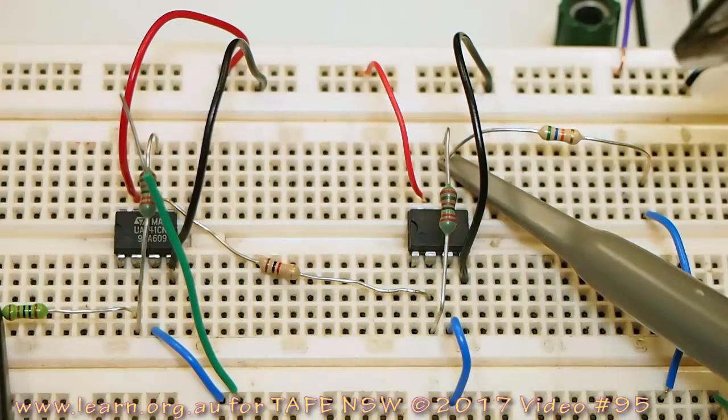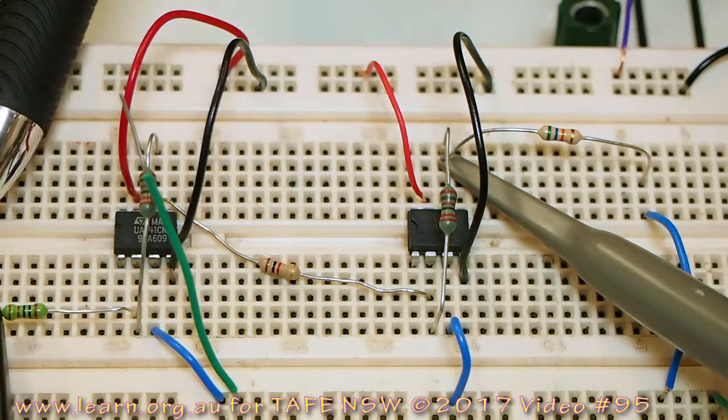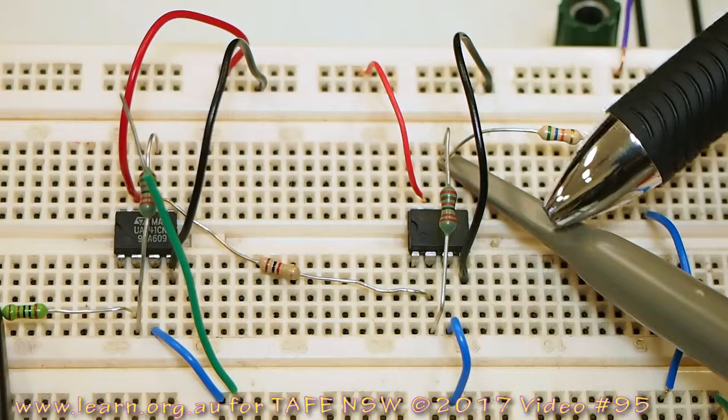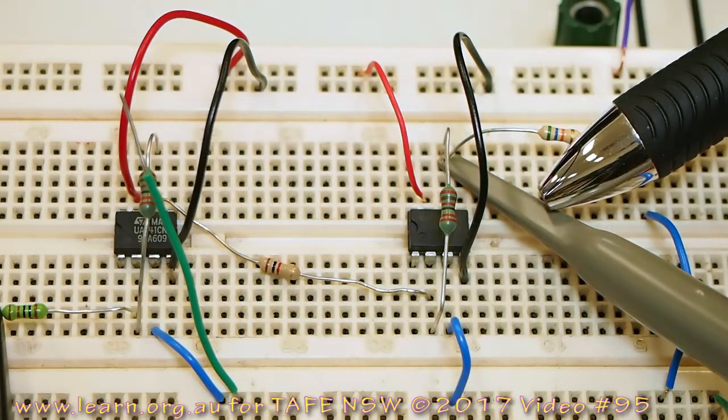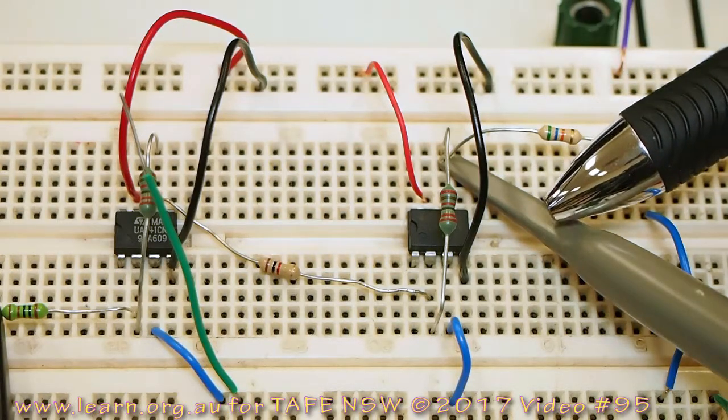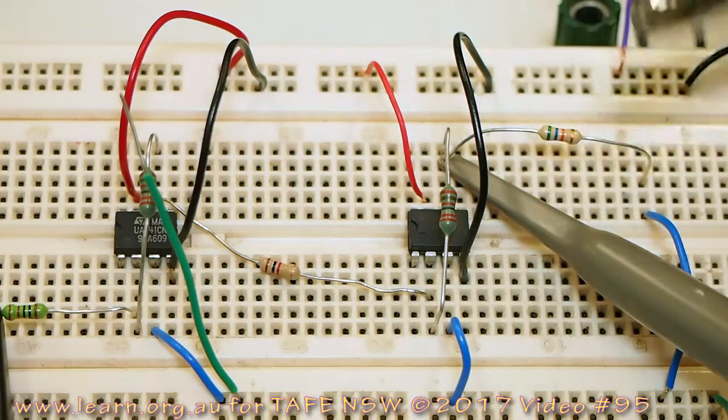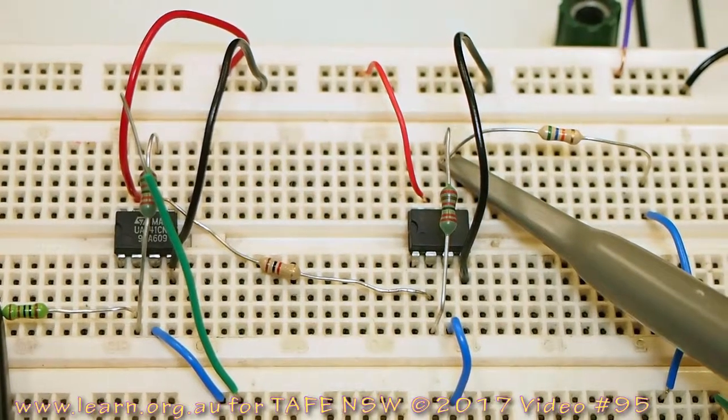Now, what we'll do, we'll take the camera and we'll have a look at the oscilloscope and get an idea of exactly what's happening with this circuit. Remember, we were putting in about 50 millivolts peak to peak, and on the output channel over here we should be expecting to get about 24, 25, 26 volts peak to peak before it starts clipping. Alright, I'll just spin the camera up now to the oscilloscope.